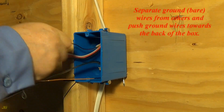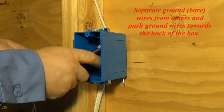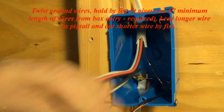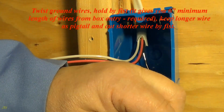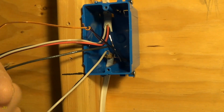Separate ground, bare, wires from others and push ground wires towards the back of the box. Twist ground wires, hold by fist, it gives you 6 inches minimum length of wires from box entry, required. Keep longer wire as pigtail and cut shorter wire by fist.